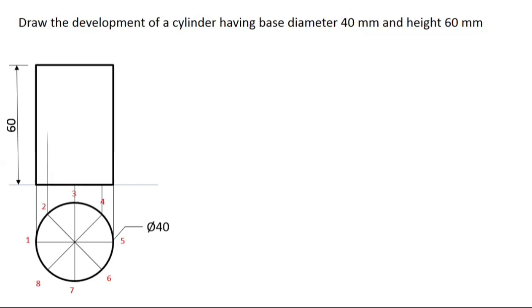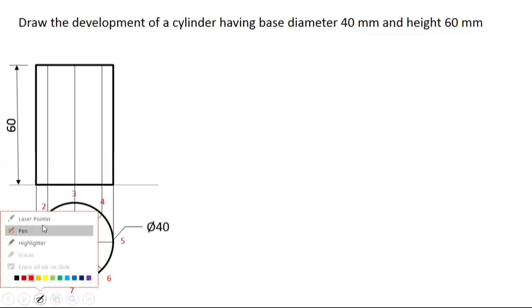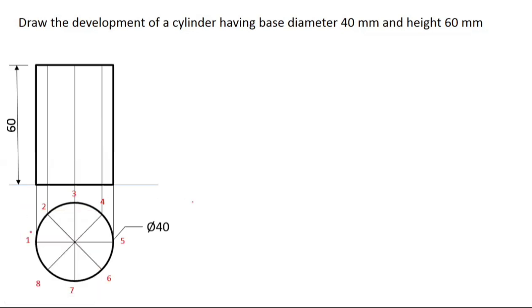First of all, take the projection inside, just like that. Now tell me, what should the naming be? Naming should be like that, na? This one would be 1 dash. 8 will be visible first, then 2 is hidden behind, so I will name it 8 dash comma 2 dash. Then 7 dash comma 3 dash.